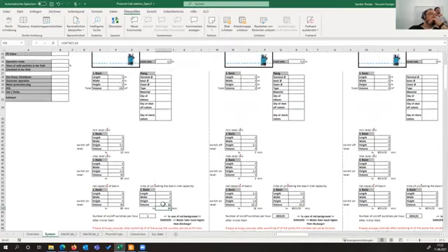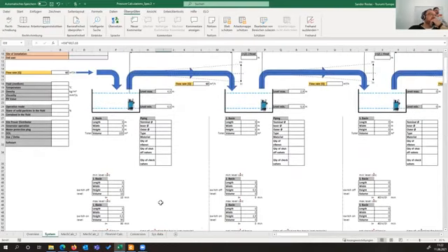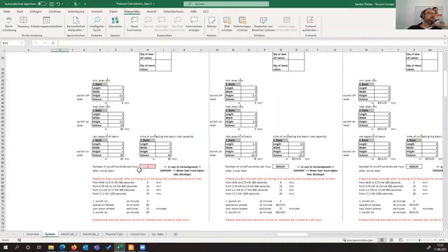So what will happen if we change some numbers? When the incoming or the inlet flow is increased sometimes for several reasons, but the pump will not be changed, then we will immediately get an alarm because the incoming flow rate is higher than the discharge.